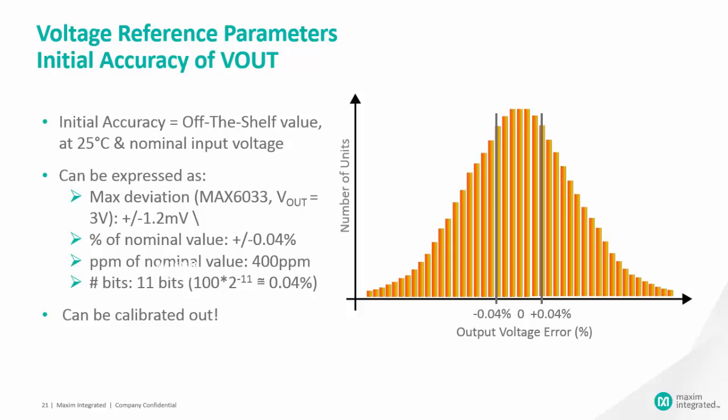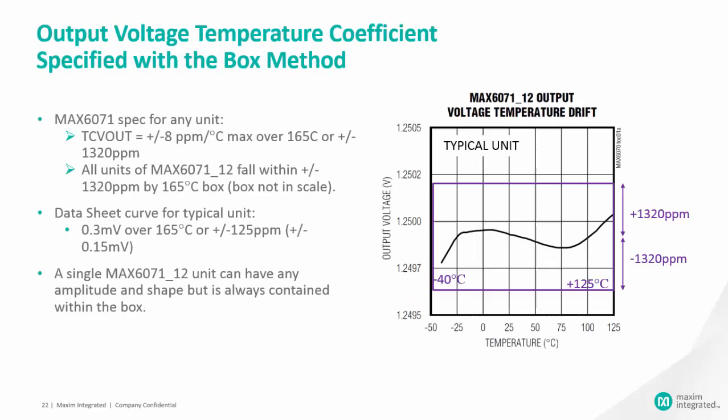Use of sensing and forcing pins helps avoid additional errors from parasitic voltage drops in the PC board. Minimization of the board's mechanical stress and maximizing board cleanliness all help accuracy. For more on this subject, please refer to Maxim's tutorial number 719.